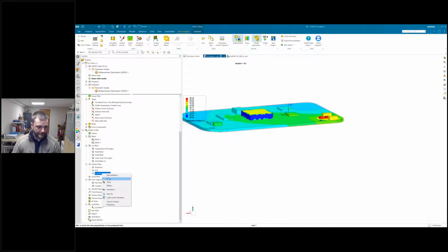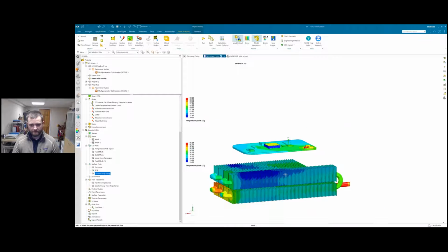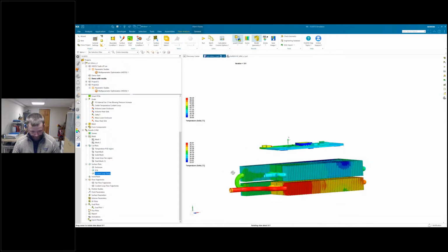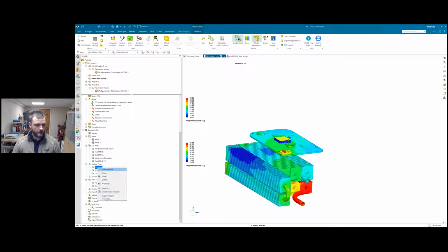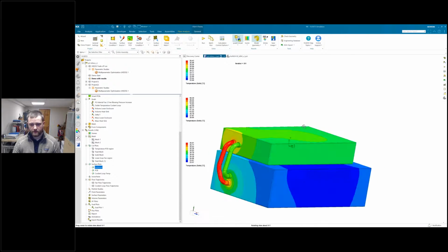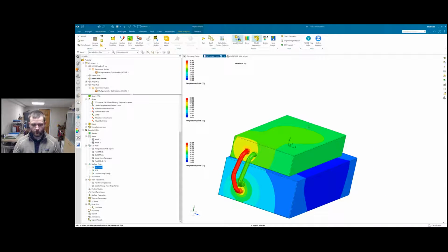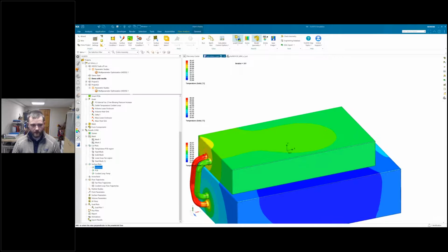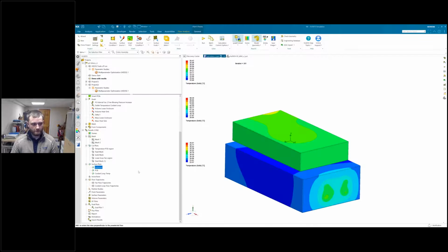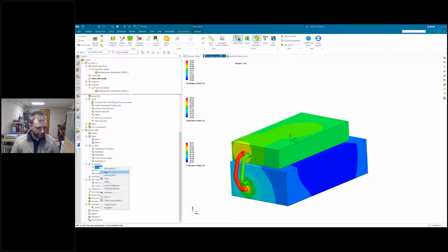We can also look at the temperature of the coolant loop. So we can look at the actual temperatures of this radiator, the hot and the cold side. And we can also take a look at the enclosure, with an overall temperature look at the hot pipe and the cold pipe. Maybe we want to know, is this pipe getting too hot based on the material? If this is some type of rubber, is it going to stand up to that temperature? We want to know that. Let's go ahead and hide those.